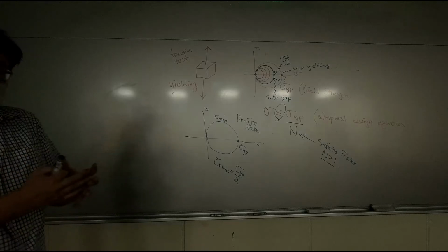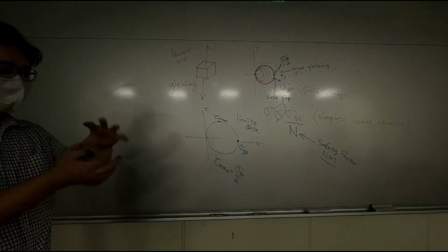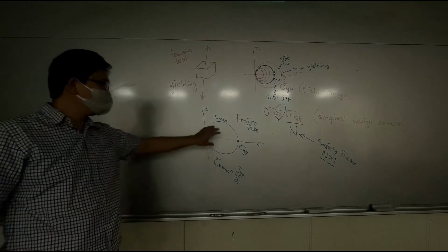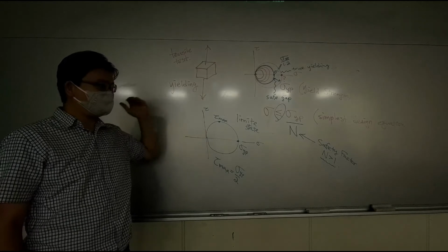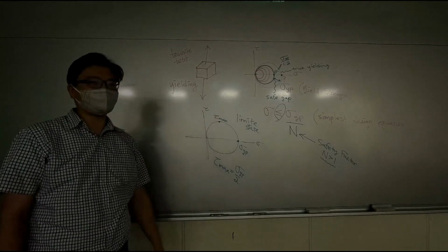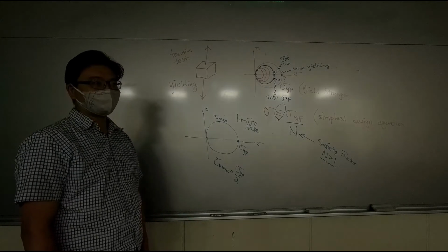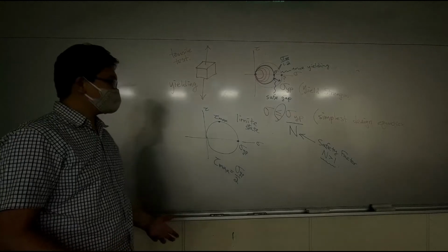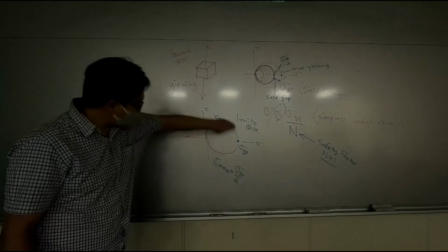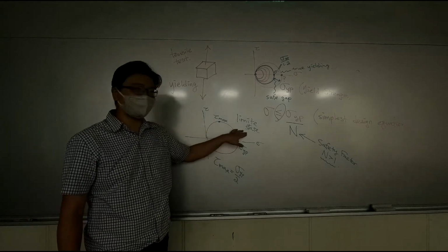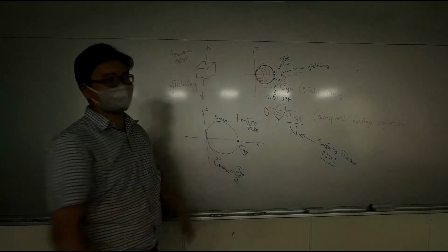So for every metal, no matter what kind of design you have, you can only allow shearing force up to half of your yielding strength. Okay, make sense? Because this Mohr circle represents the limit state. You cannot survive a load condition greater than the circle.